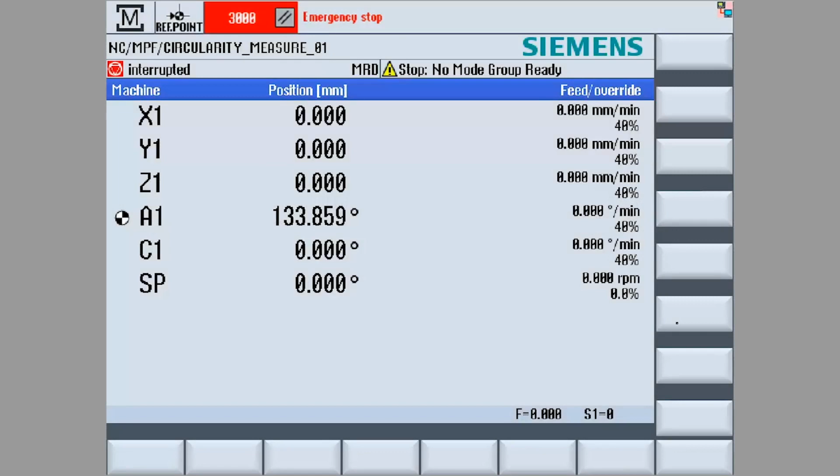Hello, this video shows how to enter data for a non-Siemens synchronous rotary motor. The steps here assume that a unit configuration has been carried out and that the line module has been configured. Normally, with a Siemens motor, all necessary motor information is automatically input into the drive data. With a non-Siemens motor, this is not the case and the data must be manually input.